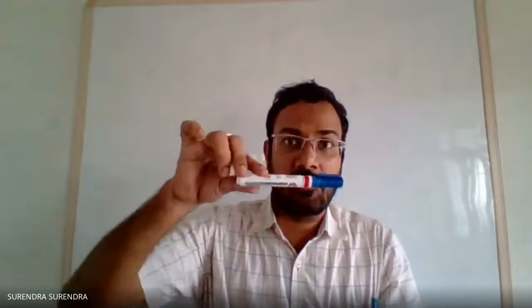Cone is resting on one of its generators on HP with the axis parallel to vertical plane. Cone base diameter 60 mm and axis length 80 mm. Draw its projections. Same as the previous problem, that was a hexagonal pyramid, here it is a cone. Initial position is the standing vertical position, and in the second position it is resting on one of its generators on the horizontal plane.